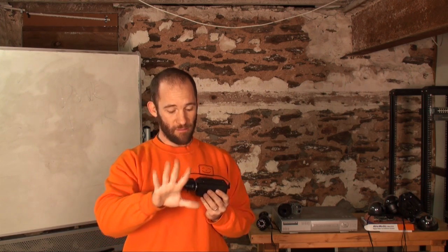When they talk about frames per second, the first thing you have to look at is the live view FPS. The live view FPS is when you are looking at the monitor and watching all the cameras in actual real time, how fast is everything moving? It will say 30 frames per second, or 15, or 7.5. If you're in the guard shack surveilling the parking lot, that's how it's moving. If it's 30 frames per second, you're seeing it in real time. If it's 7.5 frames per second, you're seeing things jittery.